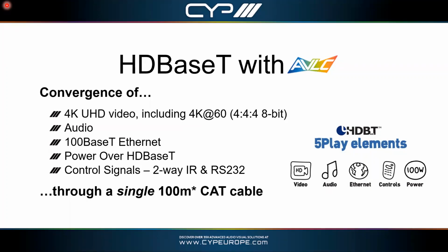Be careful with what you're buying there, because a lot of manufacturers say they're HDR compatible with these systems, but actually all they're doing is passing the metadata and the brightness data across, but you're not actually getting the additional color depth and chroma subsampling. Whereas with this system, you really do. The other thing to note about our system is the adaptive bit. There are other manufacturers that have taken on the VLC technology, but as far as I'm aware, none of them have made it adaptive.